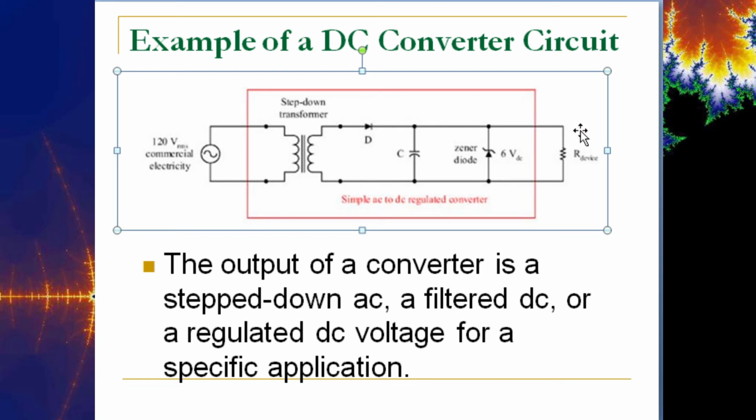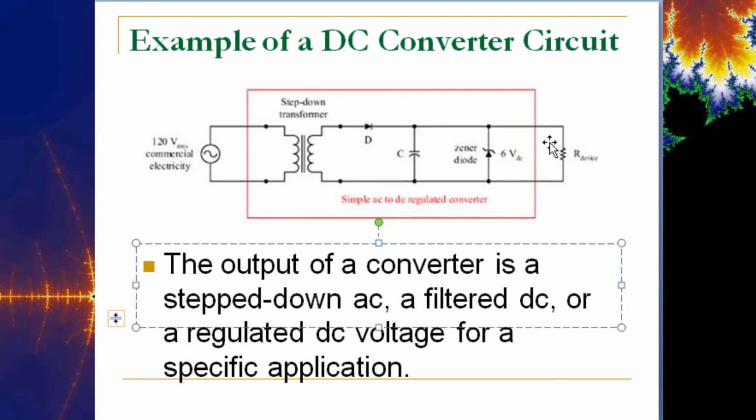So you get more of what looks like waves on an ocean, as opposed to just humps that go to 0 and then another hump that goes to 0. So you refine that transition from peak to peak until you get to the point where the peak to peak transition just looks like a flat DC signal. Okay, so that's always the goal when you do a power supply: you're trying to reduce that ripple voltage on the output by adding some other circuit components in here that give you a more flat, more reasonable, constant DC signal. Okay.